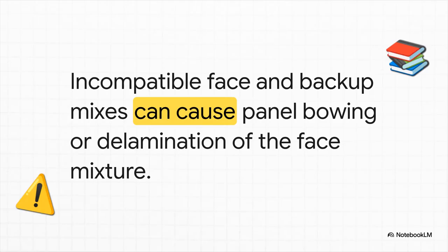Okay, here's another good little exam tip for you. Again, you don't need to be a mix designer, but you do need to understand the risks involved. If you see a product using two different mixes, like a face mix and a backup mix, you need to know that if they're not compatible, they can cause serious problems like bowing or delamination down the road. It's all about being aware.